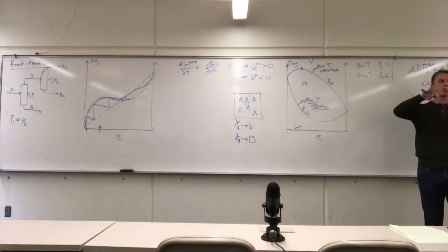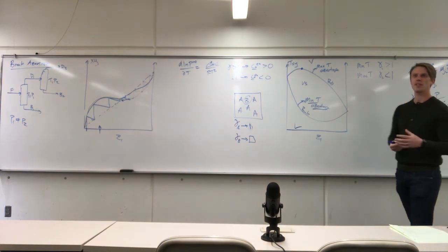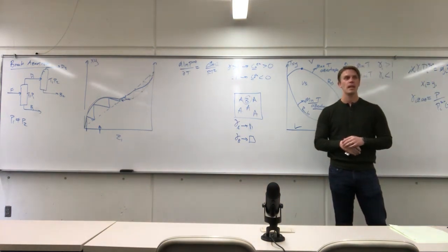Based on the curvature of Gibbs free energy, whether or not you have a pseudo-stable fluid or an unstable fluid, it'll tell you how those two things phase separate. Has anyone ever heard of the term spinodal decomposition? Spinodal decomposition is a phase transition mechanism of an unstable fluid. And it's exploited quite often in making high surface area composite materials.